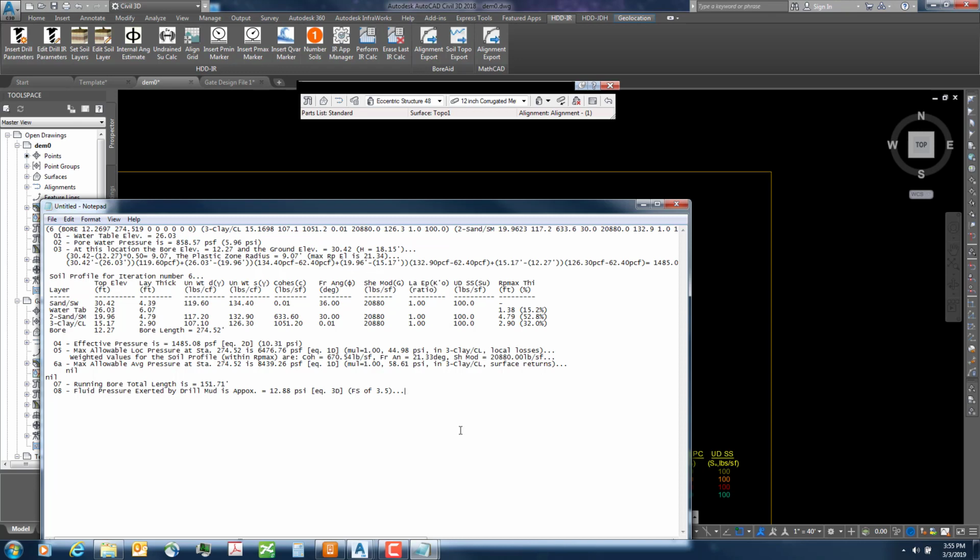In my program, I can actually set it up to export this for every interval into a text file that can be submitted with the report, so that whoever wants to follow along, essentially a reviewer, could take any interval they wanted to. In this case, what was interval 6 on the previous 30-foot iteration length, and they can put these elevations in, and they can calculate a pore water pressure. Here's the water table.